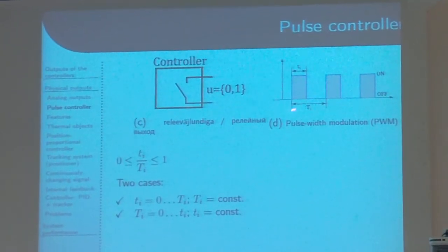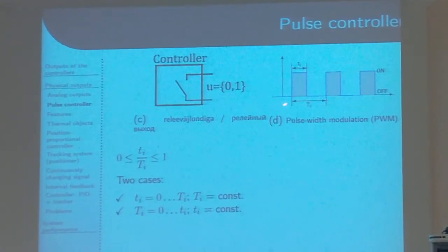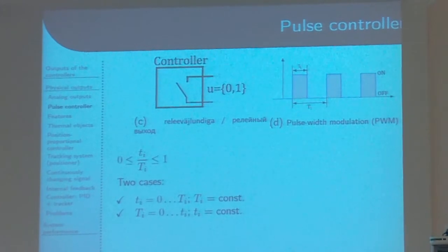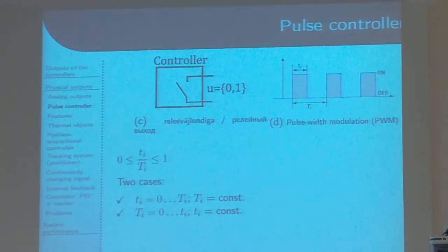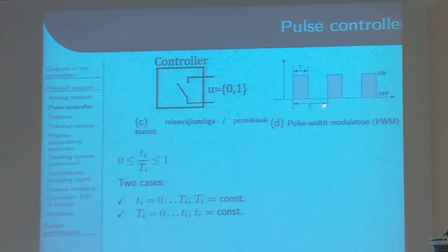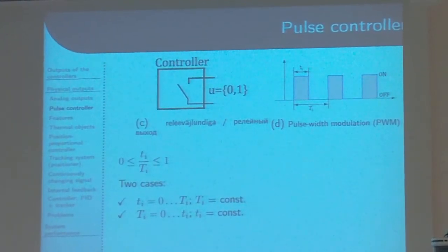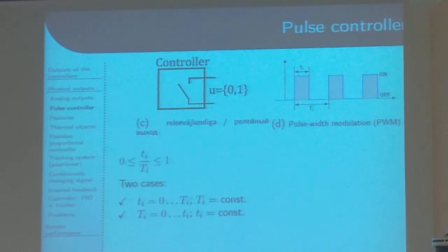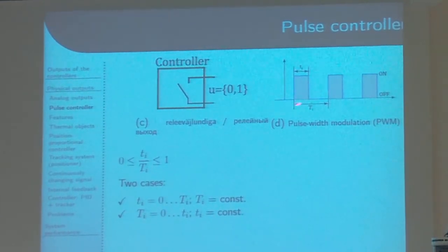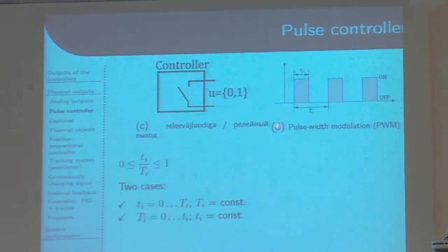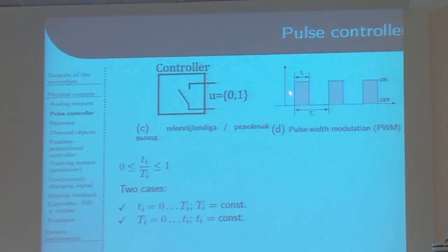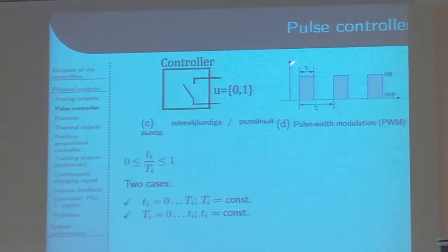With that technique, we always have a parameter, the time during which we are observing our signal. In our Omron controllers, this is called CP, or control period. This is the period of observation. We also have another parameter, the pulse width.